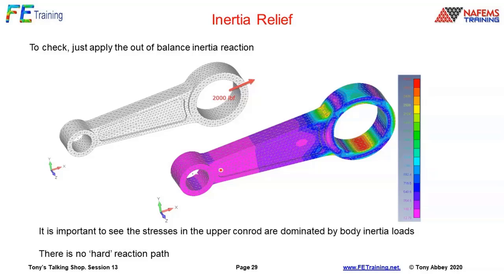If you just use this to fix up a load, say, here's the load applied here, I don't know, put it in balance, well, what does it represent? It's this kind of smeared body load. If it does represent genuine inertial loading, then we're in good shape. Otherwise, again, it's a bit of a nonsense. So just be careful about how you use inertial relief. There's a lot more to inertial relief, but this is just skimming the surface of it.